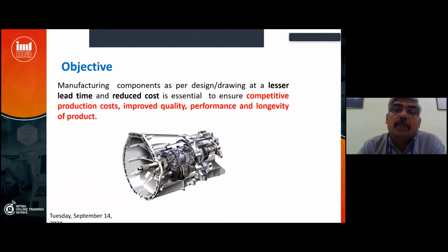Or the way you write the program: whether you write the program on the machine or offline, or you use CAD CAM, or do you have a second level, third level of team to evaluate somebody's program. So I write the program and voluntarily give it to somebody else to evaluate, and it goes to the second. That means if approval comes from 3 teams, yes, this is the best way of cutting and there is no error in the program, I can put it on the machine, close the door and run it. There is that possibility. Actually, these are all exercises we did in many companies. We got very good improvement.